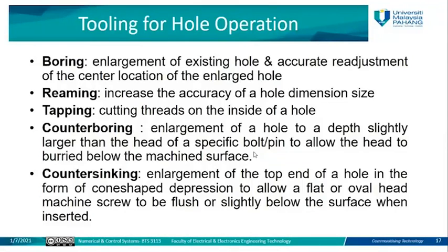Reaming operation here is to increase the accuracy of the whole dimension size. Dimension means you are going to focus more on the diameter or the radius of this hole. So you are going to make the reaming operation on this one. Tapping is for cutting threads on the inside of the hole. So if you want to cut some threads inside the hole, this operation they call the tapping operation.